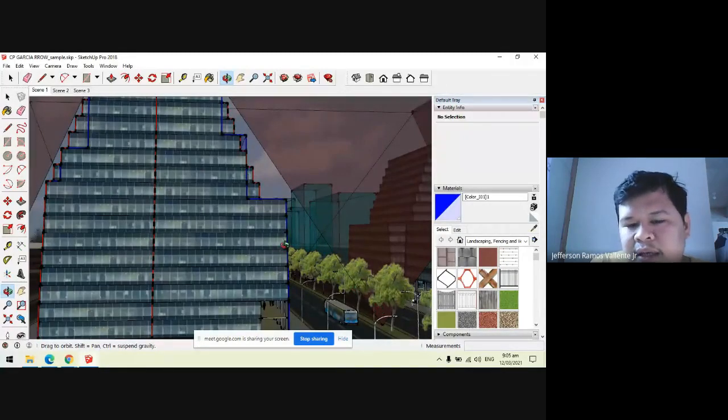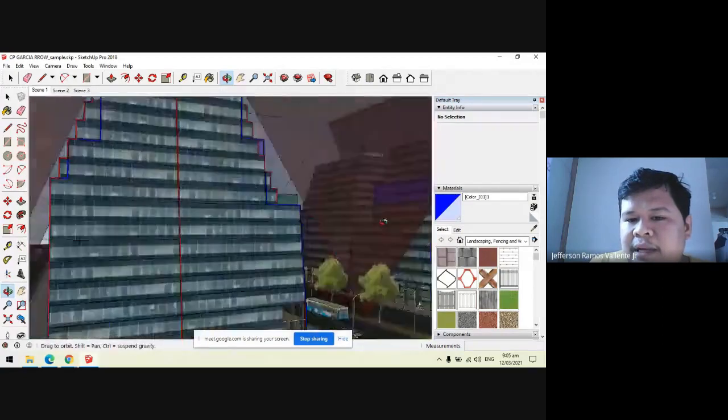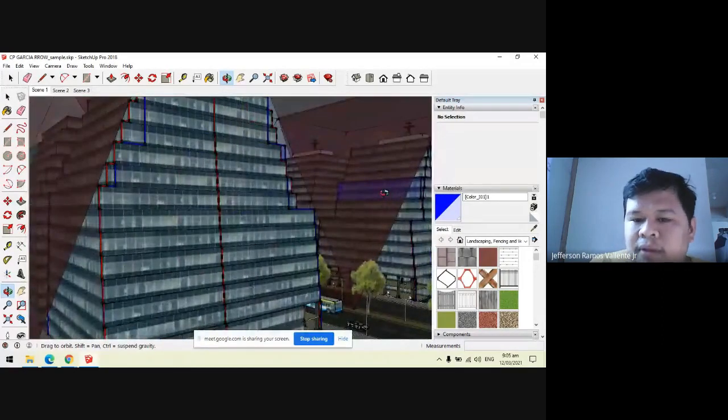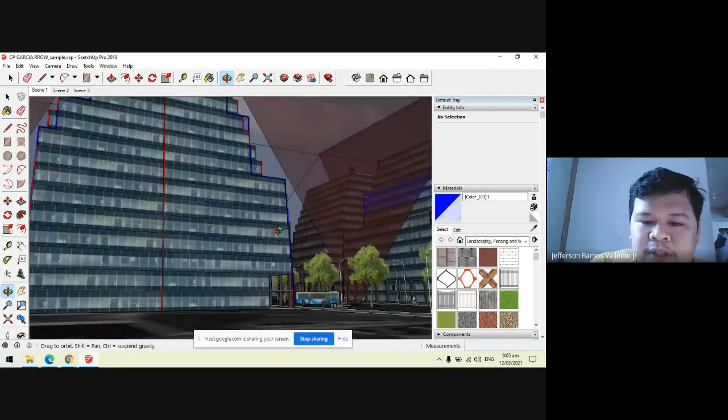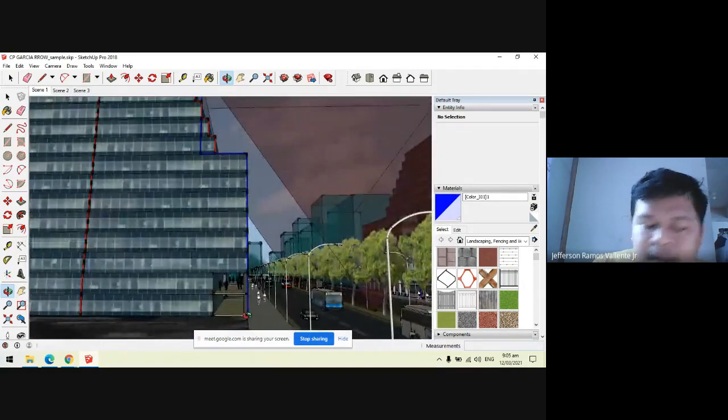So if you just make it vertical, when a person looks out, they would see the other side of the building, over there. So, that actually restricts your view. So, at the 8th story, the building will taper. So, that's the secret behind buildings at 20 stories, why they taper when they occupy the property line. Unless, of course, your property line or your area is quite big and you want to move away by as much as 4 meters, so you don't need to taper in that case.